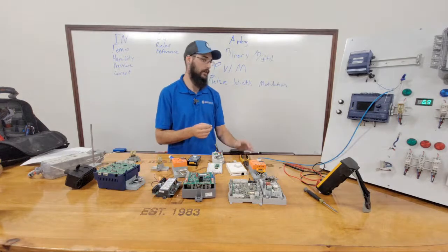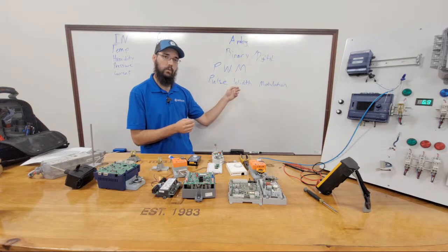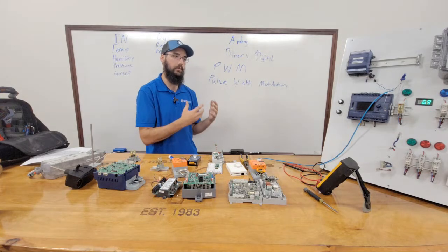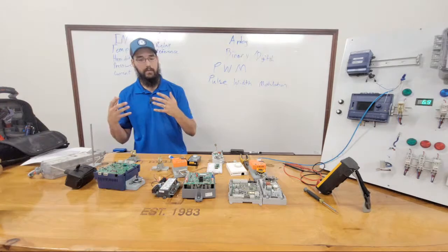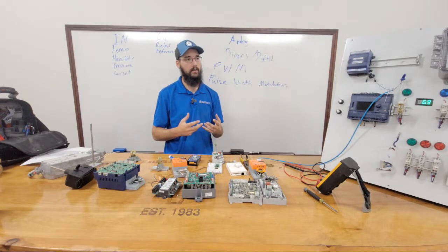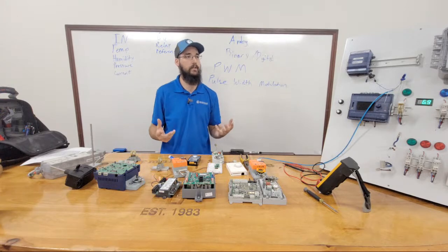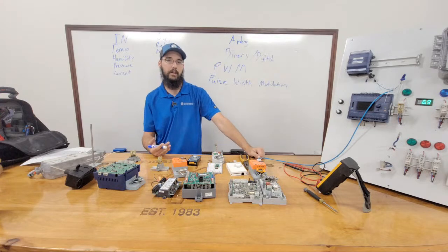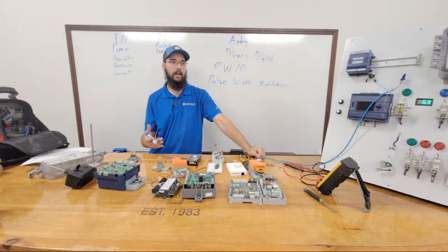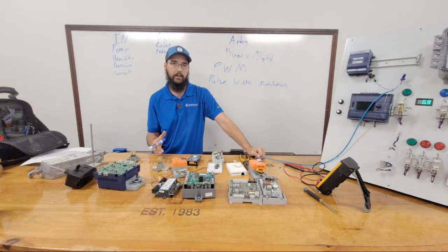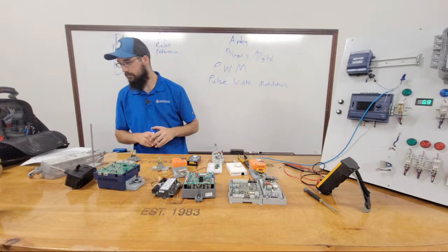And that's because the exact same technology is what makes VFDs work. VFDs use a pulse width modulated signal to create the hertz that we're trying to simulate. It's all the same technology. We just use it in different ways. Your inverters, any inverter is using PWM technology, whether it be a VRV, whether it be Daikin Rebel systems, it doesn't matter. All of it is PWM based. Anyway, I'm not going to sit on that soapbox.